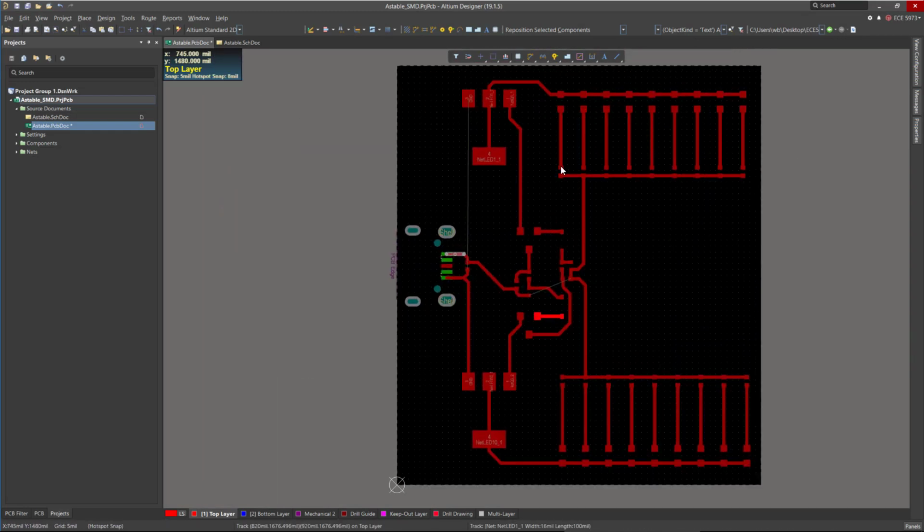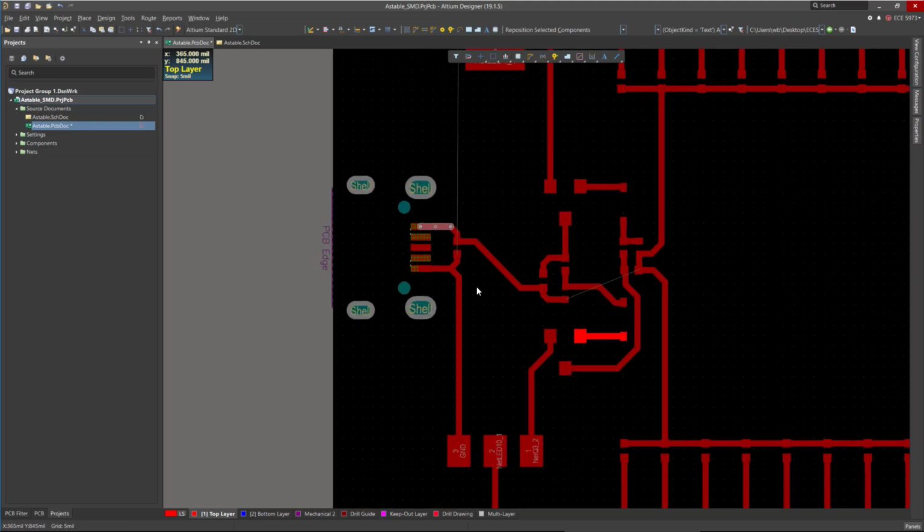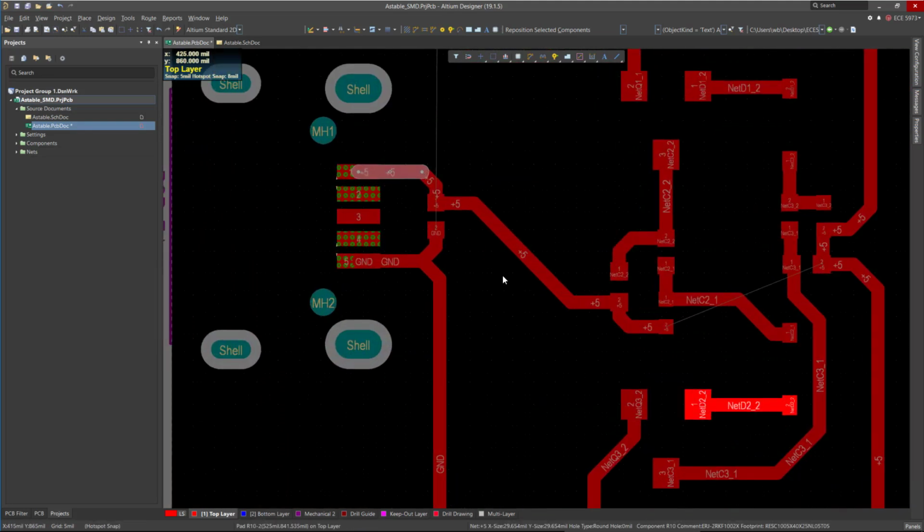So basically all these LEDs are loaded into your power line at the same time. So when you distribute your power supply, you need to make the power supply traces thicker than the signal traces.